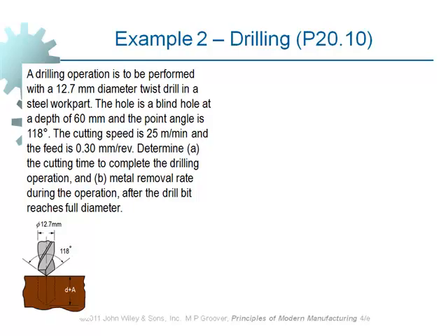What does this mean, after it reaches its full diameter? It means in the beginning, just the tip of the tool is touching the workpiece. It penetrates a little bit and makes the hole slightly larger and larger. And it takes some time for the drill bit to penetrate into the surface of the material in order to reach the full diameter of the drill. So once it reaches that full diameter, it's the time that is taken into consideration for material removal rate, which is increasing gradually.